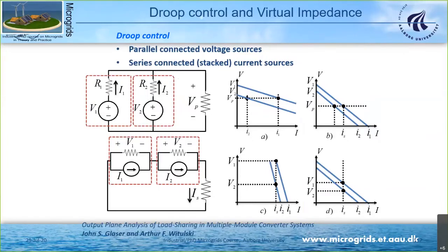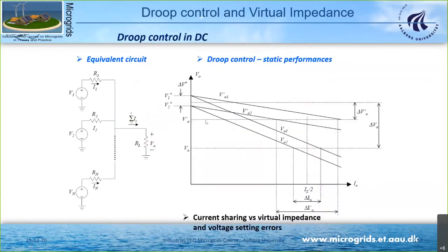Coming from AC, we can see similar things on DC. So when we talk about virtual inertias, in our case, when we talk about DC systems, we don't have frequency. So that means that we just have two variables. It's basically current and voltage, or you could think power and voltage also. So this means that we can also integrate Droop controllers by measuring the current and drooping down the voltage. The same way that we are using the Q, let's say reactive power versus voltage, here we can use current versus voltage in order to have those droops and in order to connect a number of voltage sources in parallel.